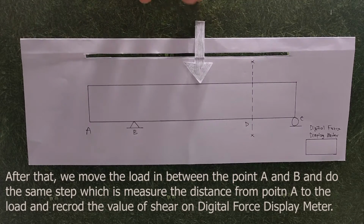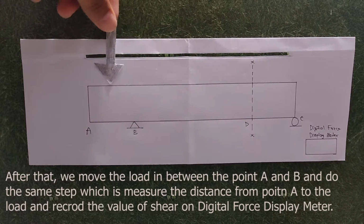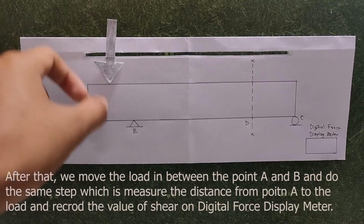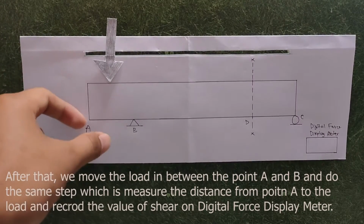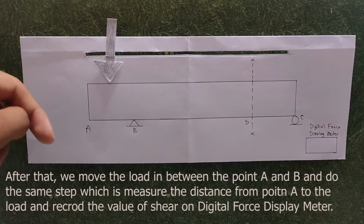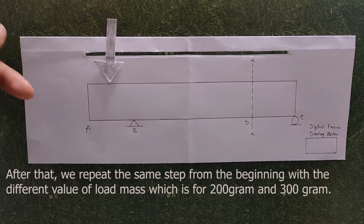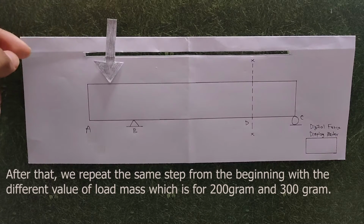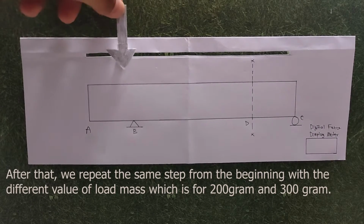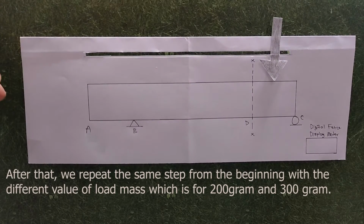After that, we move the position to the point between A and B, and we do the same step, which is measuring from point A to the load and recording the shear value at the digital force display meter. And after that, we repeat the same step from the beginning with different values of mass, which is 200 gram and 300 gram.